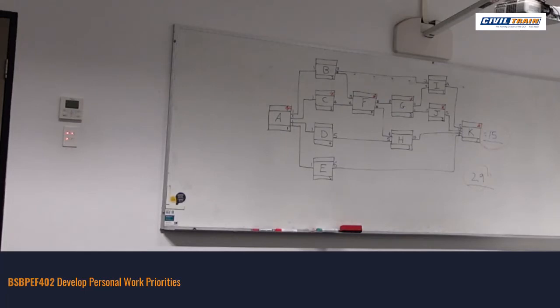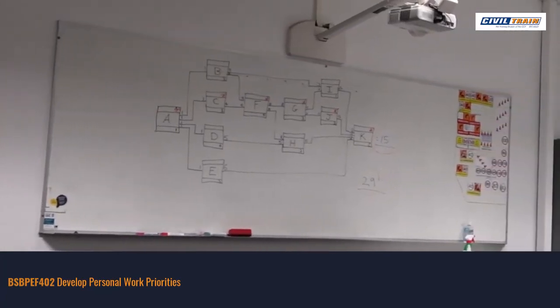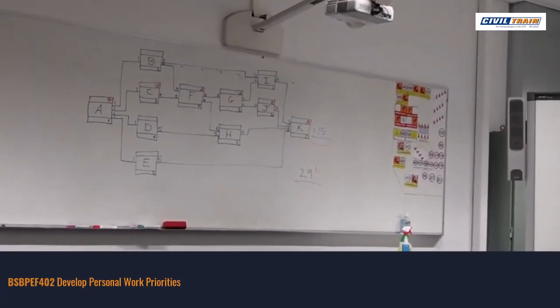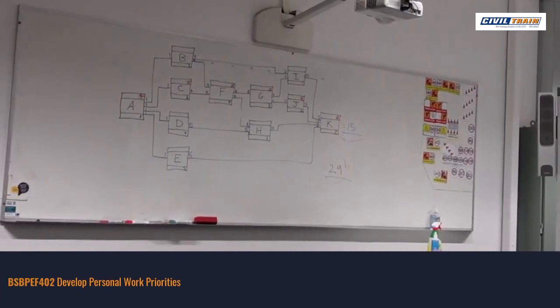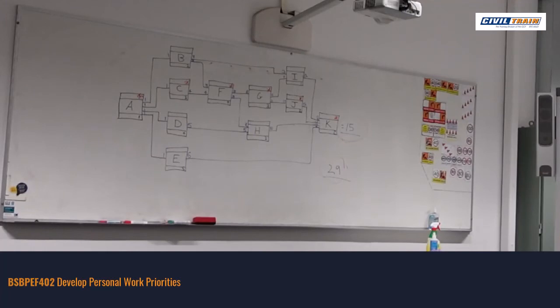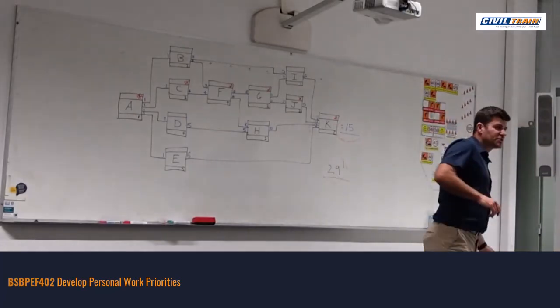Because if it was calculated on critical path method, it's the minimum number without anything going wrong. There's no buffer in that in regards to leniency, unless you would have put contingencies in. So it's 15 days. June, July, I'm going to add 2 days for wet weather, and already pre-plan that part of the process. So if I was going to put this into a bar chart,